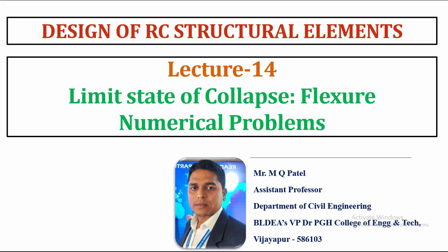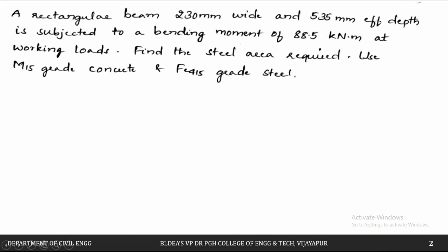Good morning, students. In this video we are going to solve problems on singly reinforced beam. So let us take this problem. We have a rectangular beam of size 230 mm wide and 530 mm effective depth, which is subjected to a bending moment of 88.5 kN at working loads. Find the steel area required.